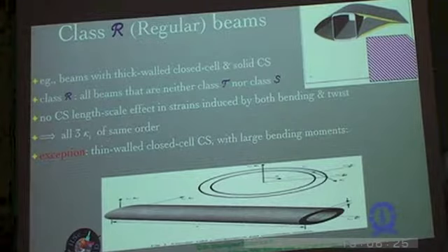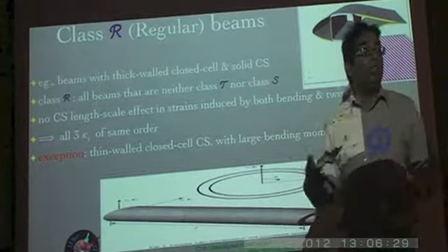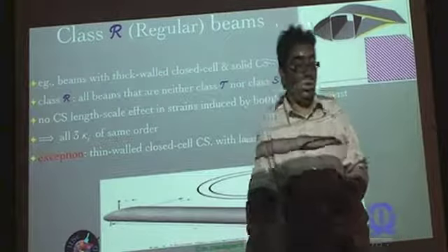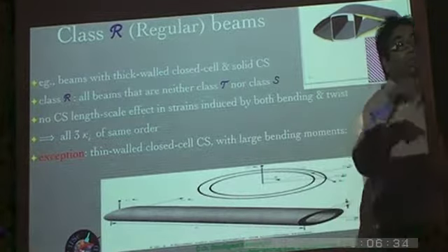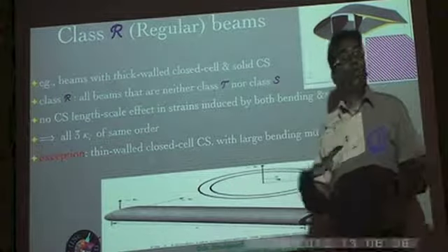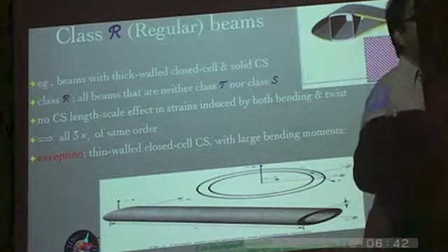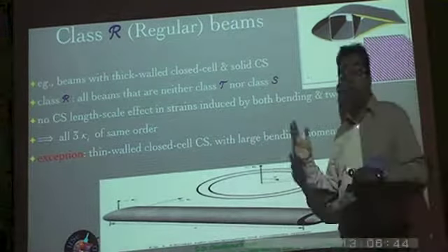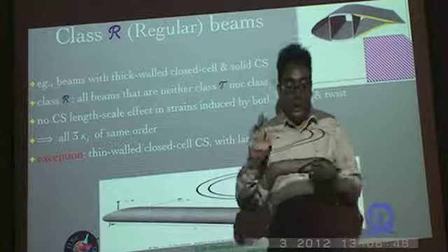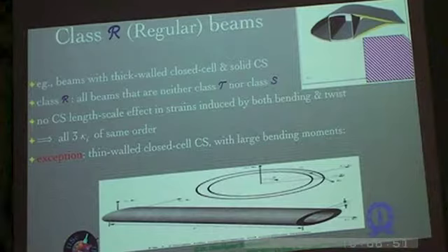But of course, if you want to deal with higher mode vibrations or higher mode stability problems for this, then you do have to include explicitly the transverse shear measures in order to see the effect. So you might have to introduce the transverse shear gamma 1,2 and gamma 1,3 and go for that 6x6 matrix for the stiffness. But of course, it still remains linear. The nonlinear effects there are absolutely unimportant.